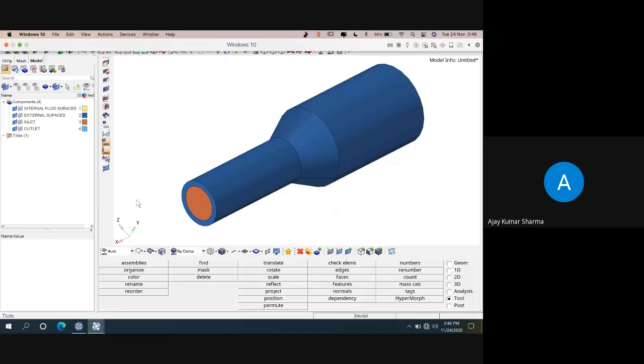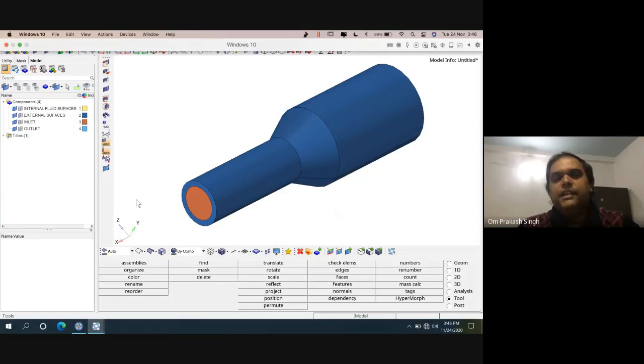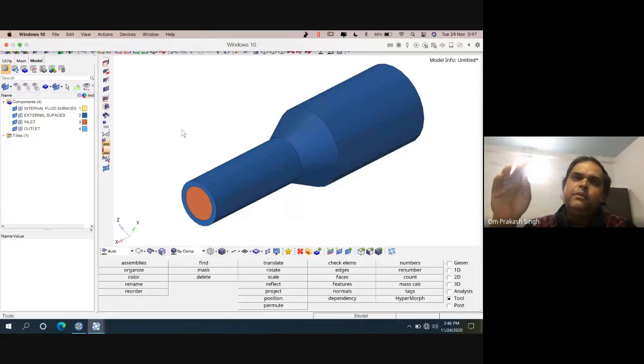Yes and no. Yes, there has to be an optimum mesh size, number one. For this reason, you see in most of the research papers we talk about the grid independent test. In a sense, there is an optimum grid level beyond which the result will not change much. Beyond that, there is no point in going on increasing your mesh size. Otherwise, you will have